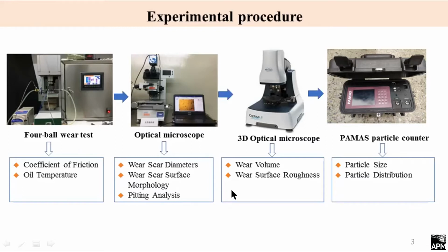Next, we use a 3D optical microscope to calculate the wear volume and measure the wear surface roughness. In the last step, we use a Palas particle counter to count the particles inside the oil after experiments.